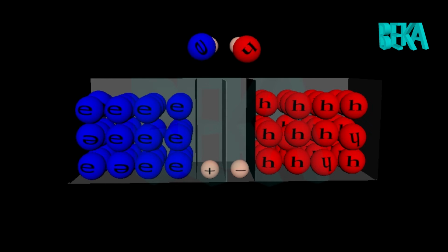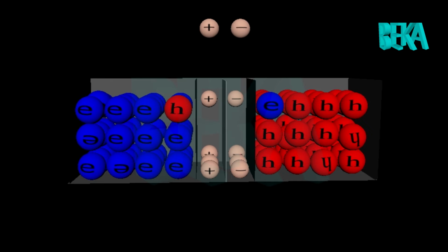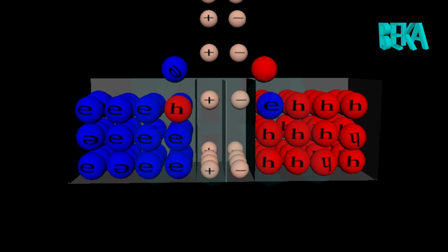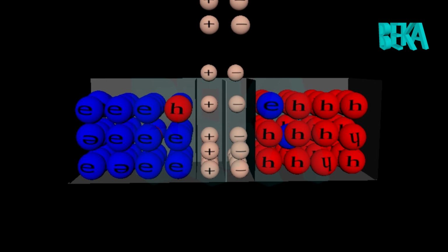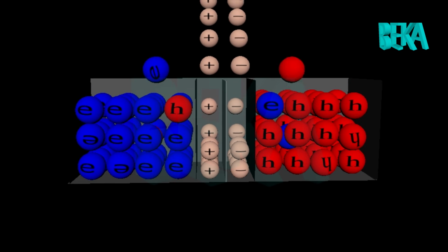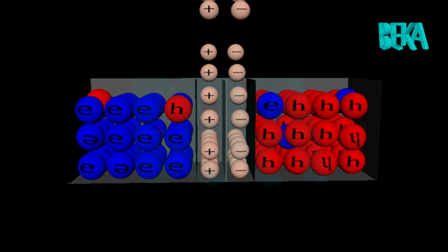When the N-type and P-type semiconductor materials are first joined together, a very large density gradient exists between both sides of the p-n junction. The result is that some of the free electrons from the donor impurity atoms begin to migrate across this newly formed junction to fill up the holes in the p-type material, producing negative ions. However, because the electrons have moved across the p-n junction from the N-type silicon to the p-type silicon, they leave behind positively charged donor ions on the negative side, and now the holes from the acceptor impurity migrate across the junction in the opposite direction into the region where there are large numbers of free electrons.